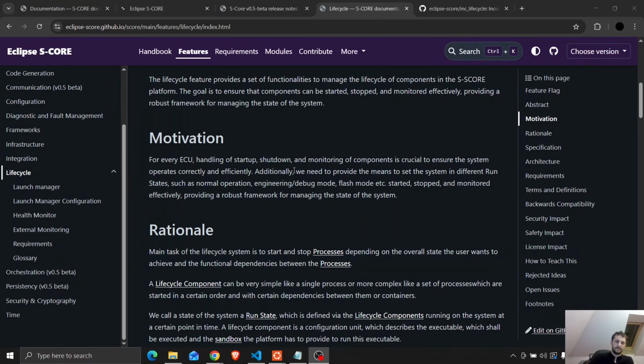incubation stage. The next feature is lifecycle, realized by Middleware lifecycle, and that is used for starting applications in a deterministic and ordered way. It also gives the possibility to define ECU states like low power mode and degraded, in which some apps can be turned off or on. This is kind of an execution manager. It also supports JSON configuration files, with the slight difference that right now they are baked into the binary, not separate files on the running target. There is also an orchestration framework that gives you in-process task scheduling if you need it.